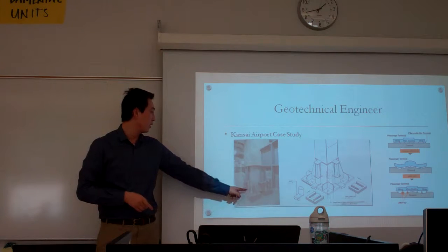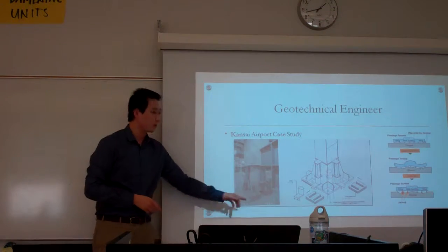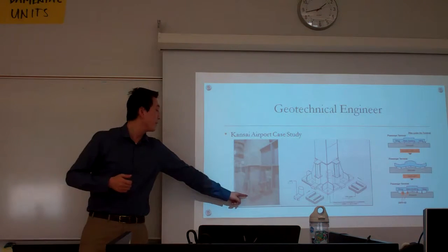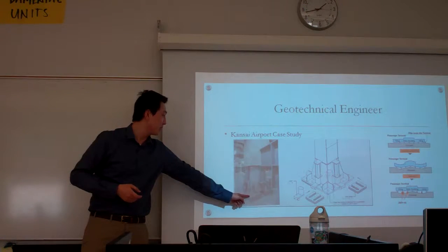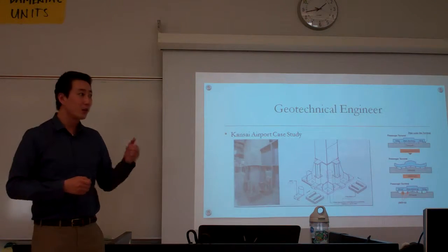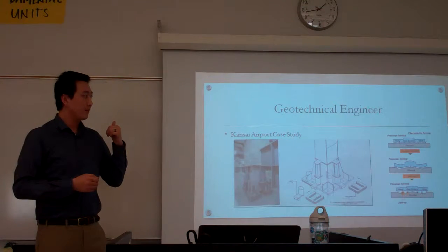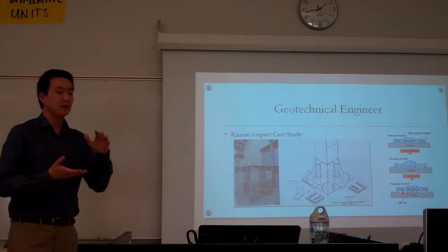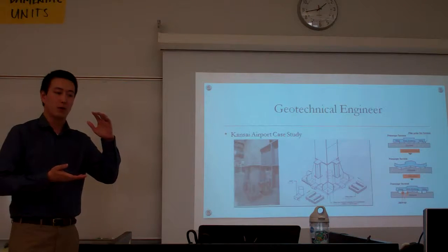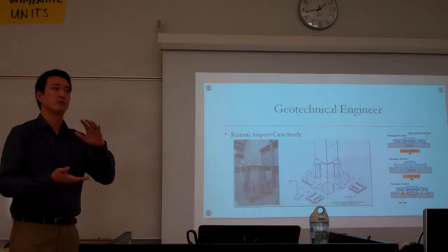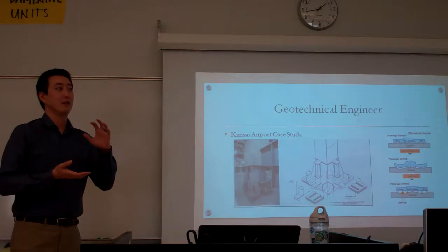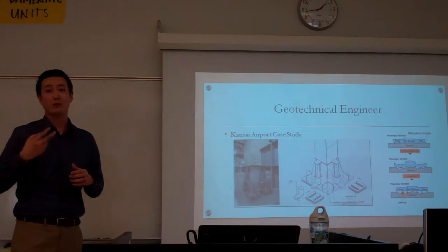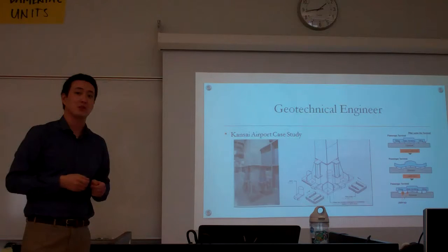You can see that typically a structural column has a base that cuts off right there, anchored into the floor. But because they needed to jack the structure up, they built that jack, and they would slide shims underneath there. The only problem was they blew the calculation by like 2 feet. They had estimated, over the course of 20 years or so, that they would need 3 feet of jack or whatever. But it ran out, and the buildings were still settling. So they had to weld 2 extra feet of jack on there so they could still slide shims under there.